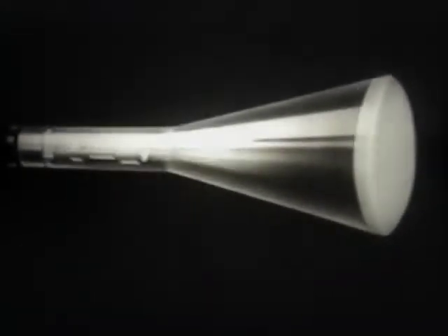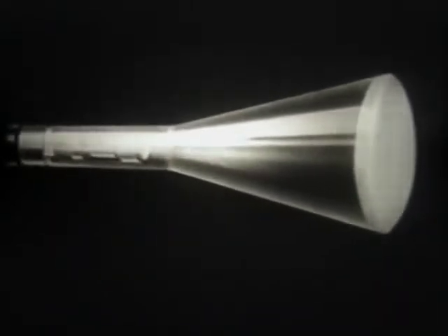At the end of the tube is the screen. All these parts are enclosed in an evacuated glass envelope. Now to find out what each part does inside the tube. The filament is like the filament in any electric bulb. When current is passed through it, it gets hot and gives off light. The real purpose of the filament, however, is not to give off light, but to act as a heater for the cathode.